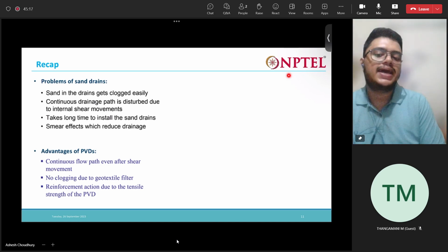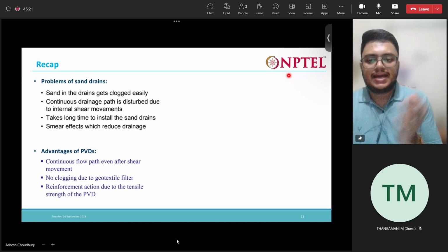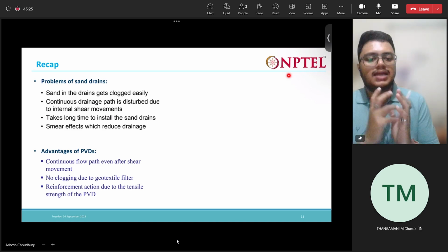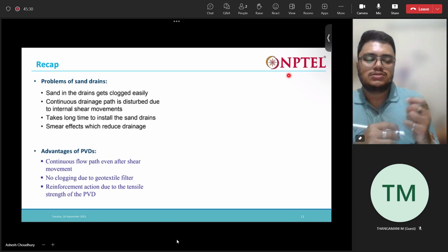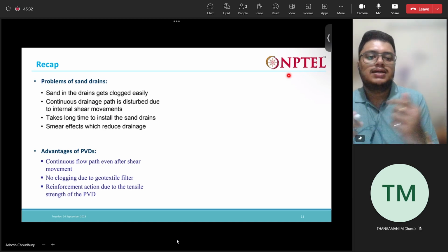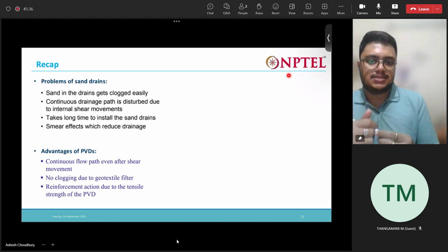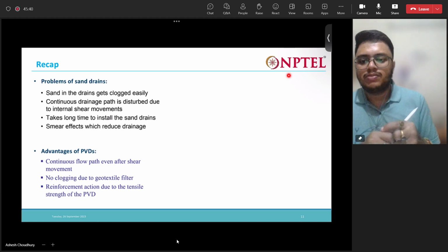First, sand in the drains gets clogged easily. What will happen? Sand drains are there, and around the sand drains you have fine-particle soil, generally clay soil. The fine particles of the clay tend to clog the pores of the sandy column.